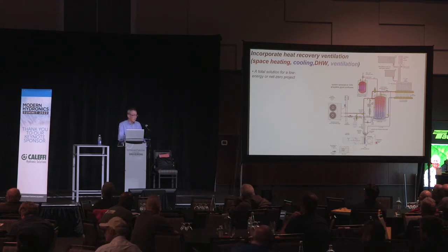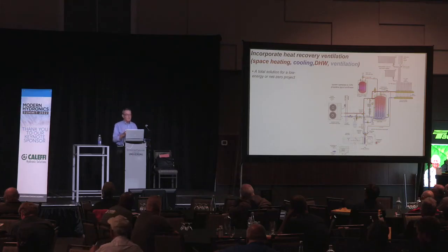And we're putting our fresh air in on the return side of the air handler, and we're simply not running the air handler at full speed just because we want to save some input power to the blower. You know, you could run at 1200 CFM and just inject the fresh air into it, but you don't really need that in a ventilation-only mode. And we're not trying to do space heating with the air handler. I want to point that out. We're only trying to bring the ventilation air up to a room-neutral temperature using some warm water from the buffer tank. So there again, that's what you can do with a hydronic system. You can't do that with other approaches. Okay.